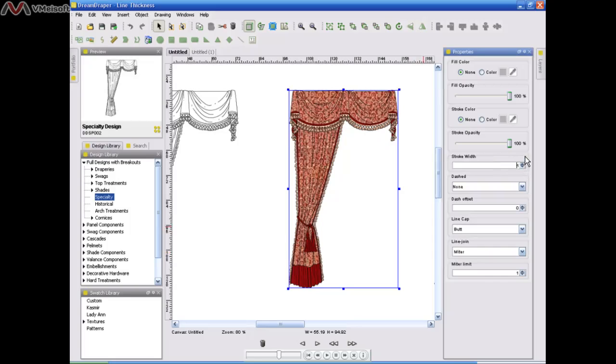There. Now you can see that the lines did get a little bit thicker, and I think you're going to be surprised at how nice that does look when you go to print. You can actually make this even thicker. I can press on my arrow key here by my stroke width and go up to 2. But I think that looks too dark. So I can actually have the difference. I can enter in 1.5 and I'll hit my enter key.